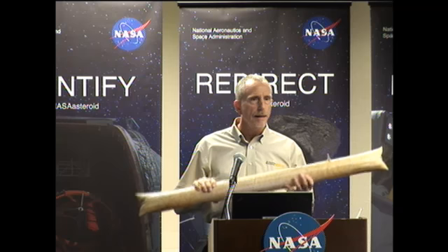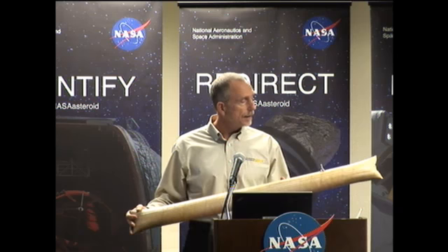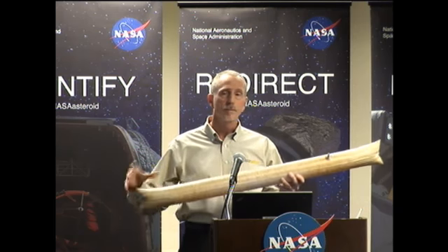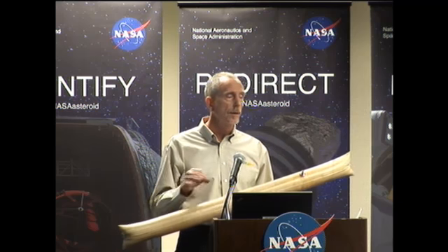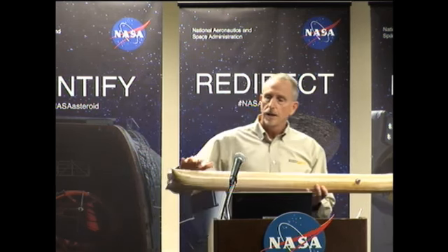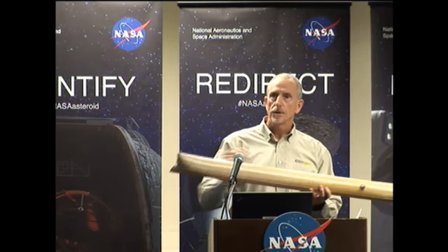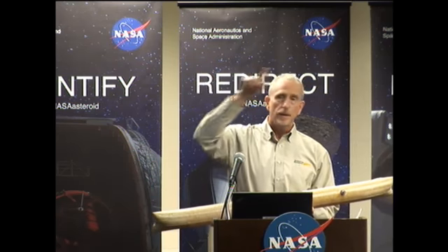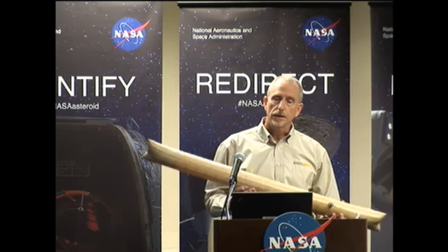This technology is very dimensionally stable and accurate. We can predict very closely what the deployed shape is going to be. It also can be designed to change its shape in relation to the inflation pressure. Also, as you can imagine, with these axial cords, if I shorten the cords or straps on one side, lengthen them on the other, I can create a curved surface. Or I can create ultimately a torus with this technology as well.